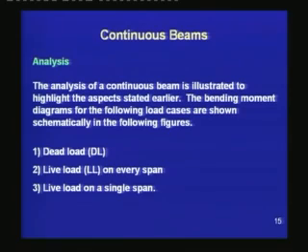Hence, in the analysis of a continuous prestressed beam, the effect of the moment due to the prestressing force should include the moment due to the reactions that are generated due to the prestressing force. With these aspects, we are moving on to the analysis in a more subjective way.